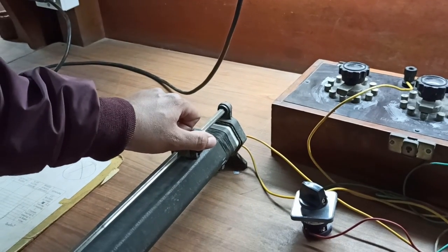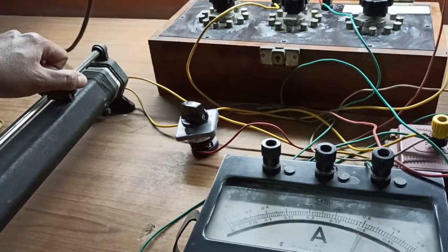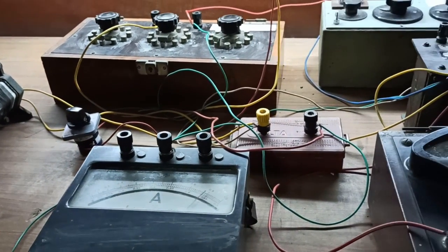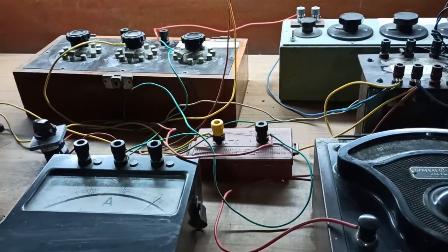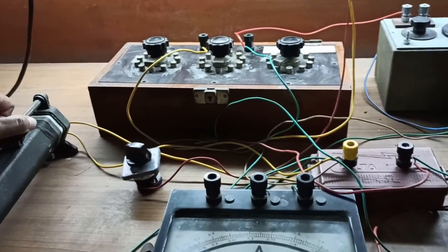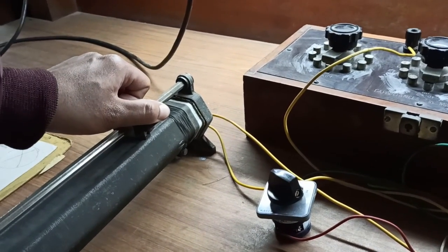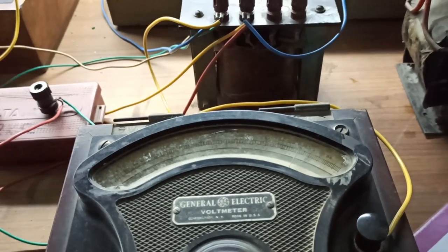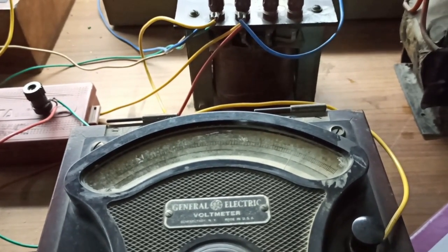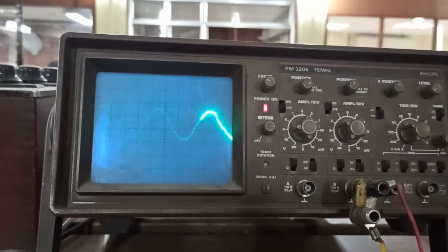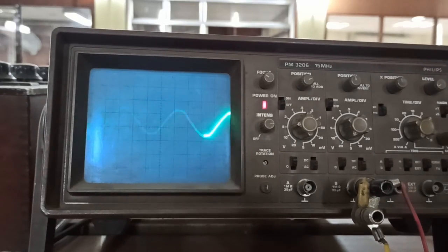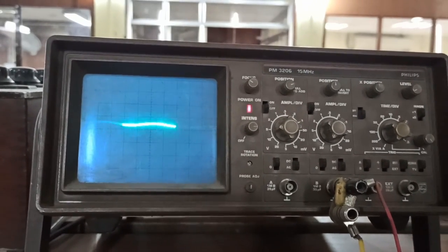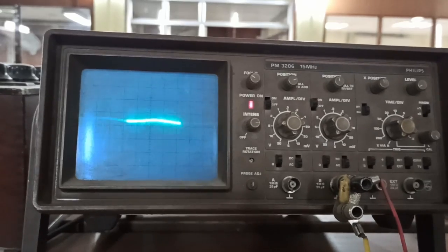Now we will vary Zs to set 120%, 80%, 60%, and 40% of its rated current by varying the burden impedance, and we'll keep Vs constant at the rated voltage. Now, using the same procedure, we have to balance the circuit and take the reading for each case.